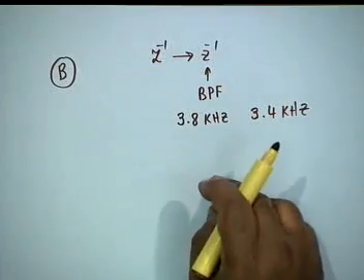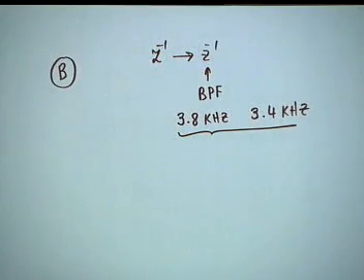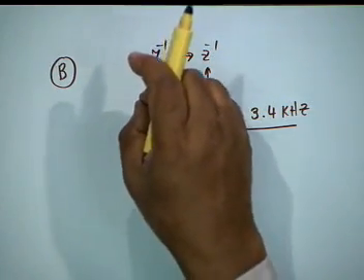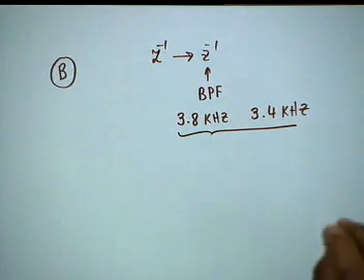And in digital to digital transformation, there is no guarantee that the new filter satisfies the stop band specifications, because the only specifications we are considering are the pass band edges. We are not considering, there is no way that we can take care of the stop band edges. Agreed? So, this is a limitation of digital to digital. On the other hand, the first route that we followed takes care of pass band as well as stop band.